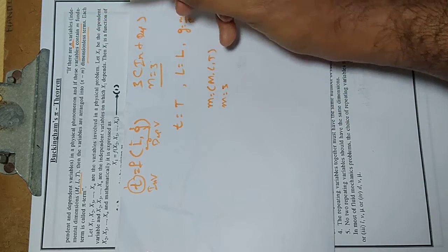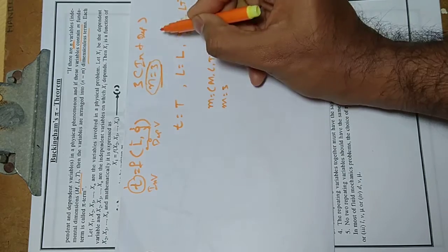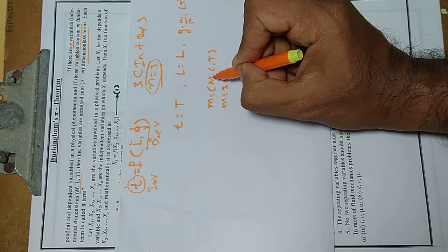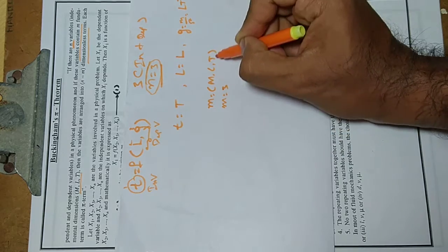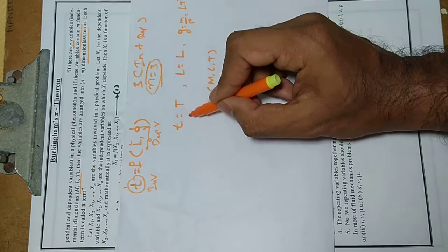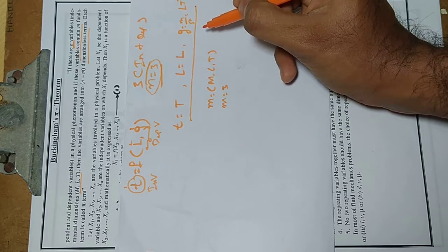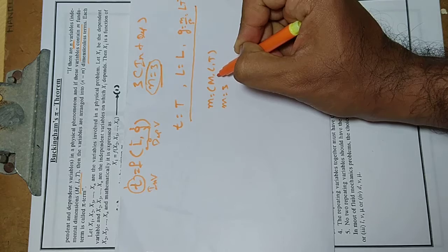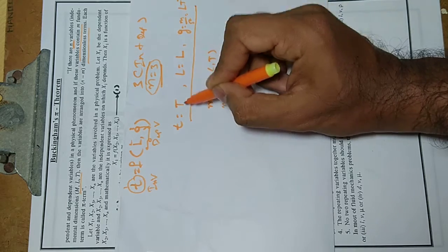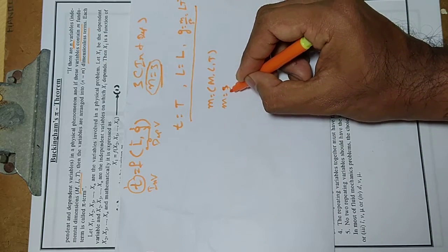In every equation you have to find out n, and then count how many dimensions there are, like mass, length, time, M L T, these three different dimension terms. Here there is no mass term; you only have L as well as T. So m becomes 2 here.